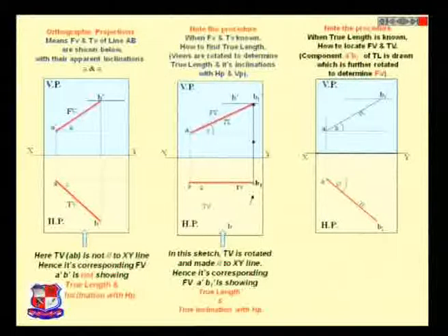Like this would be the thing. Now we want the front view and the top view. What I have done, I have just extended this line perpendicular to this point. Now what I am going to do, I will just mark this point as B2 dash.